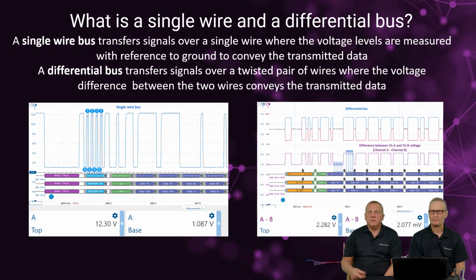But you also have to have 2 transmitters and receivers, so the computer becomes more expensive. So you can see that where it's not necessary to have all of that redundancy and fault tolerance, you can use a single wire bus. And that's well worth mentioning at this early stage, because otherwise you'd be thinking, well, why don't they just use a single wire bus all the time? Or why don't they use 2 wires or a differential bus or what's commonly known as a twisted pair? And even the act of twisting the pair makes it more fault tolerant. Thank you, Andy, you're right.